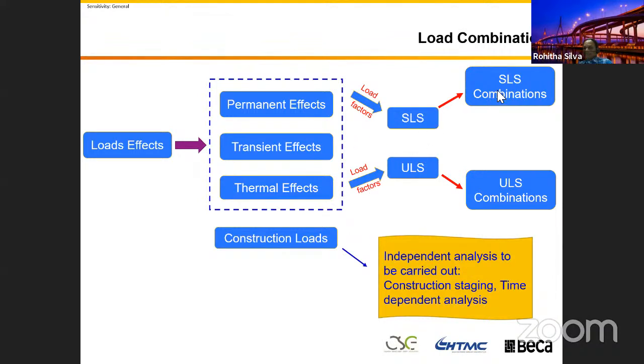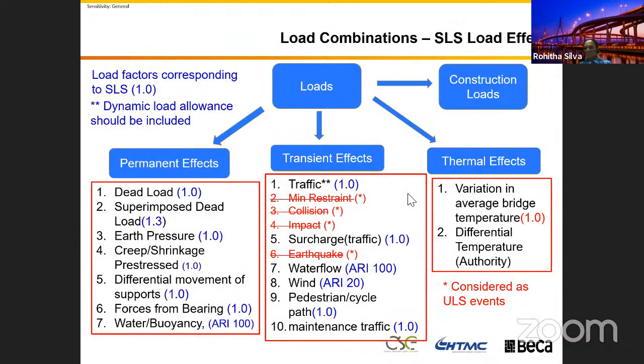Then if you know the load combination, we can calculate the actions or forces on the bridge. We call them, basically for serviceability limit state, bending moment, shear force, axial force in any members, or torsion. Bending, shear, axial, torsion. If you know those, you can design your bridge structures and detail them in a proper way.